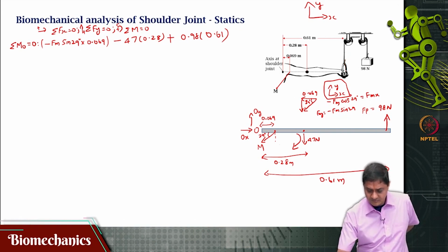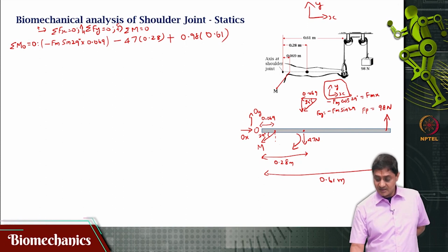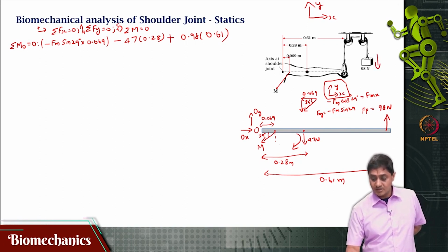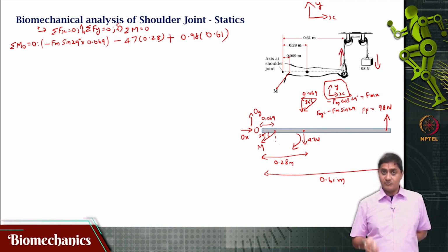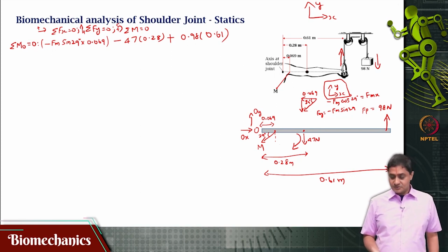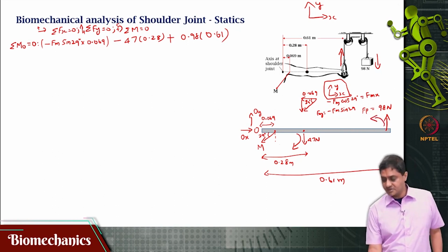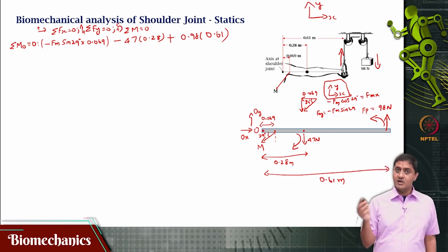Remember, because there is a pulley, here is where the action of the pulley is, here is where the action of the weight is downward, but for that person, because there is a pulley and rope involved, he will be feeling the load here like this, upwards, positive x axis, positive y axis, right. So, that force will cause a counterclockwise moment like this, because about this pivot O, it will cause a counterclockwise moment.